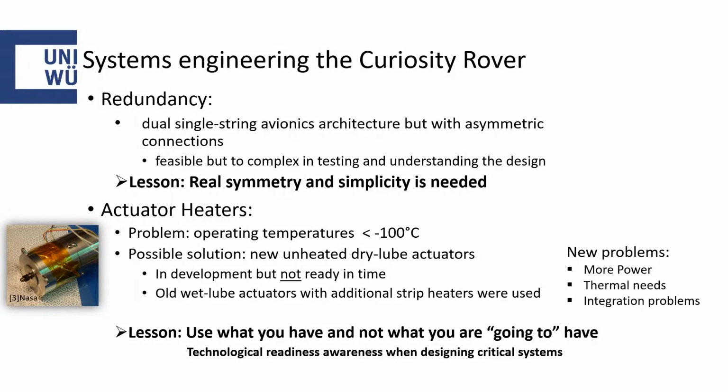And the lesson there, for the later mission, the Perseverance mission, was make it a real symmetry and do it more simple, straightforward. Don't overthink it. Don't make the system too complex, and ensure that you have documented every step on the way and every outgoing and ingoing source of interconnection, so other teams of other subsystems can easily understand what you're doing and what the interconnections are.